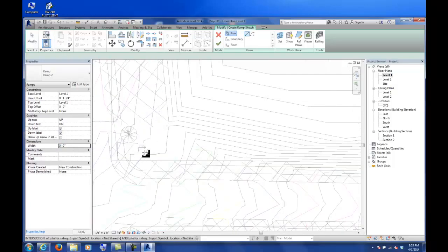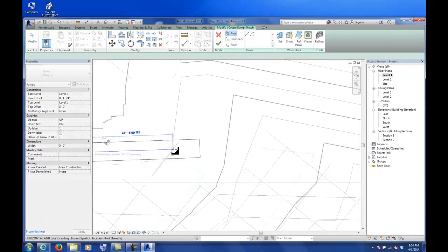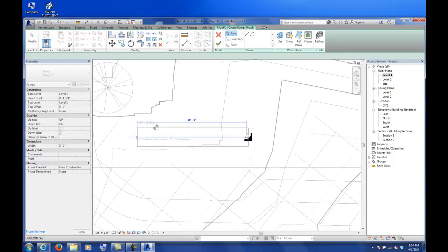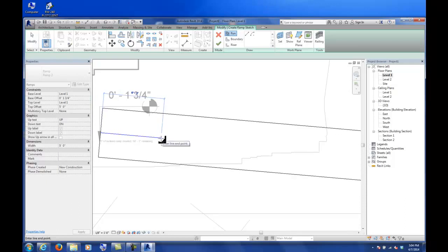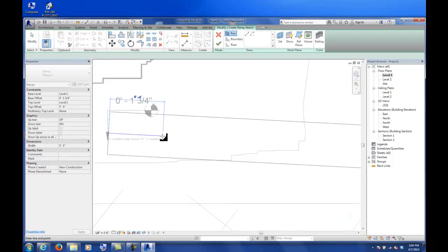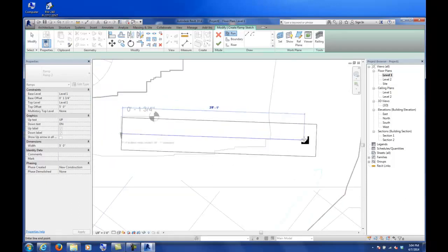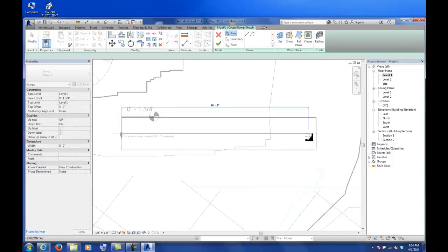I can now draw, and you would draw a ramp by run. So here's the option here, kind of like with the stair tool. Remember when we went over that briefly? You draw here, and just like with the stairs, it'll show you, okay, I've got 58 feet left to go in order to get up to this top level. And it already has built-in ADA requirements in it.